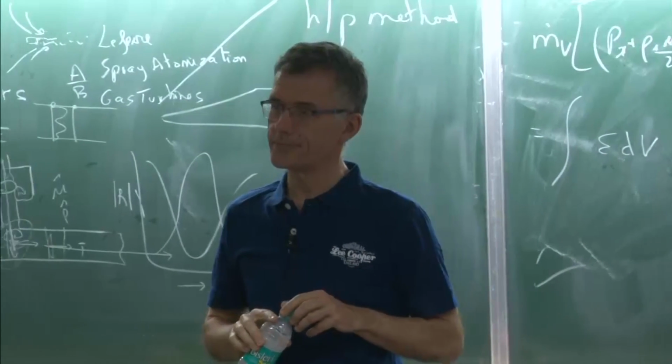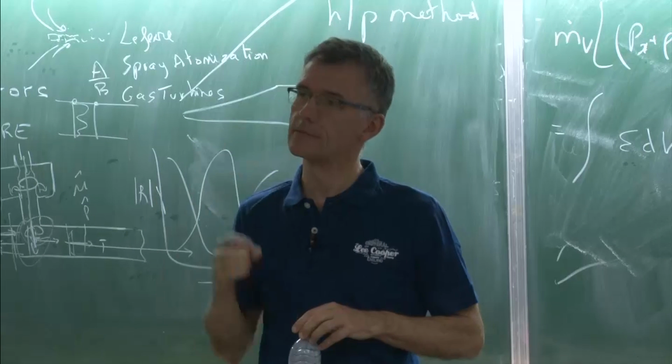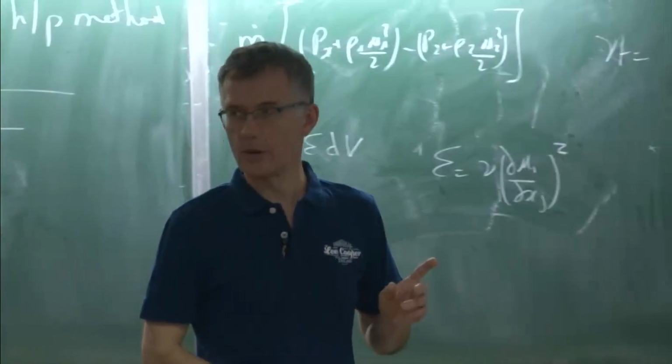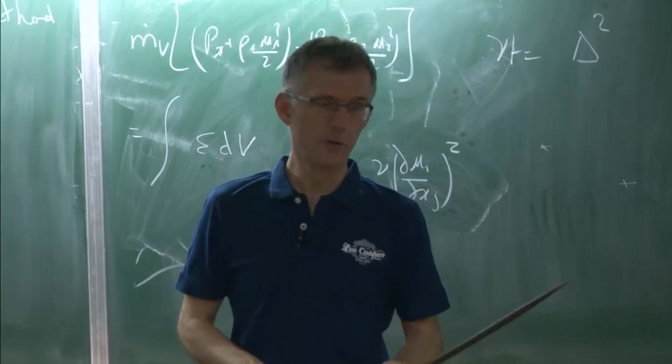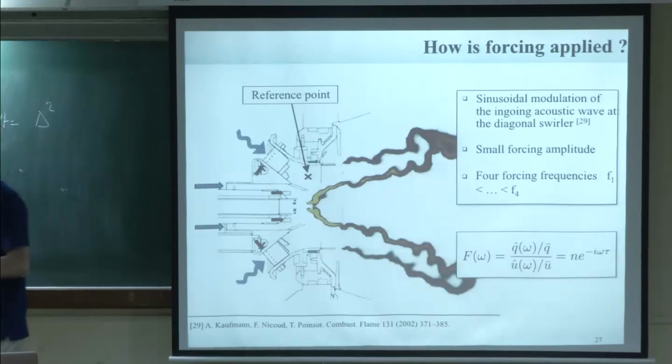What I observed is different compared to the system when it gets unstable on its own. When you do this, the engine should be stable. That means you have to use non-reflecting boundary conditions at the outlet, because if it is already unstable, it's very difficult to excite it. It's just not possible. If it is unstable on its own, you have to stabilize it before you can do the forcing. That's just the way it is.